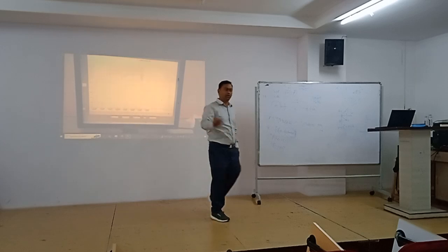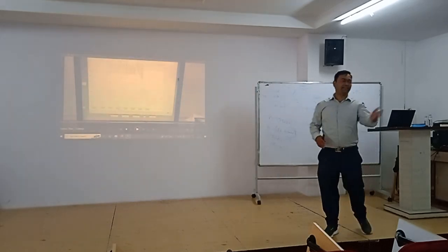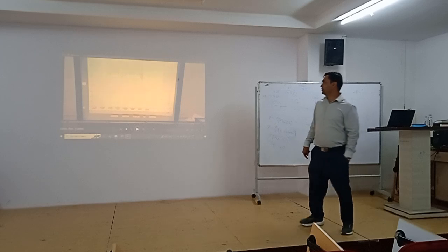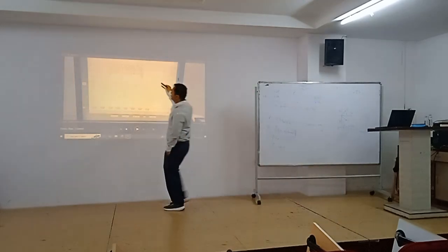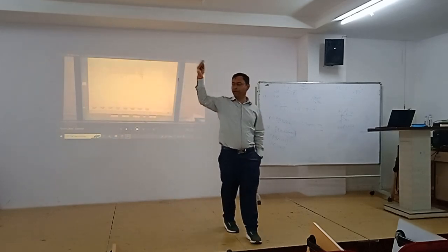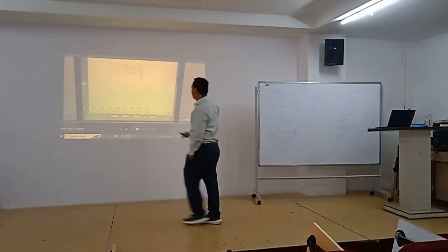So once you tune your controller, then you put any set value, it will achieve in the same manner. So actually earlier the value was 100 and tuning was not so proper, that's why it was oscillating. Then we changed the value to 50 and we also tuned the controller. Because of that, it's achieved.